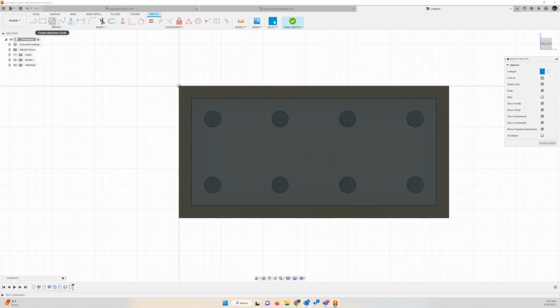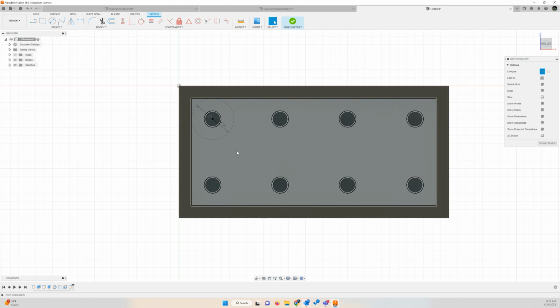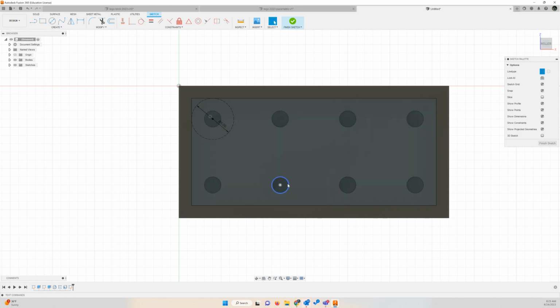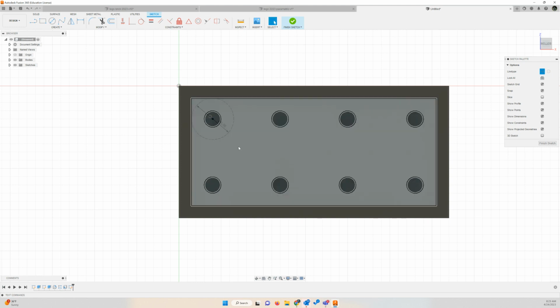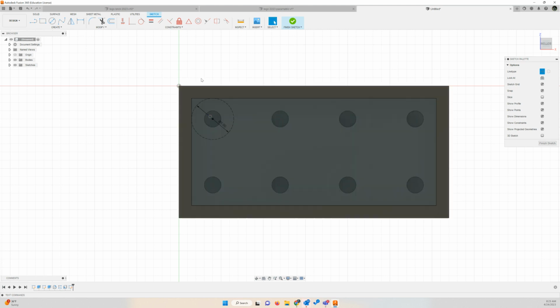First thing I'm going to do is draw from the center point there. That's one of my top connectors. I'm going to click and I'm going to draw my 5 millimeter circle. Now it's already positioned because I used the center point of the top one. Now, imagine I had 4 of these circles. My bottom connector will touch all 4.